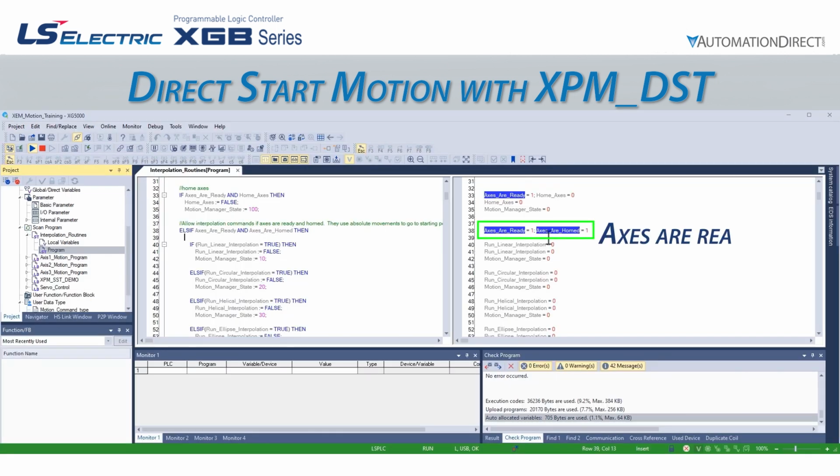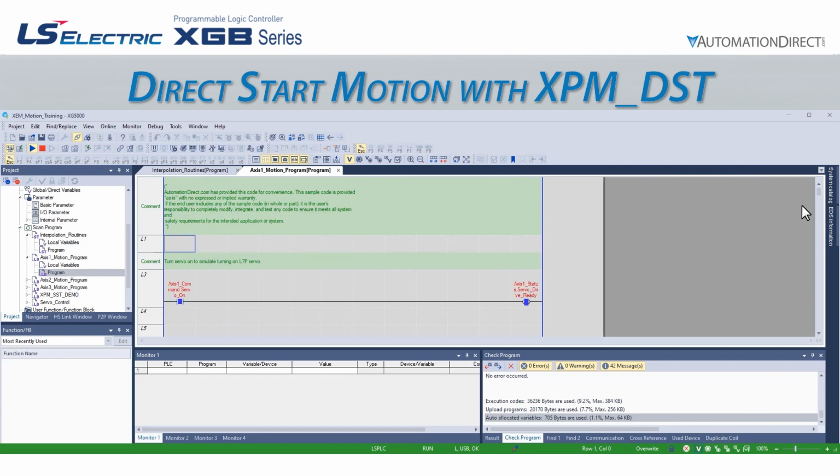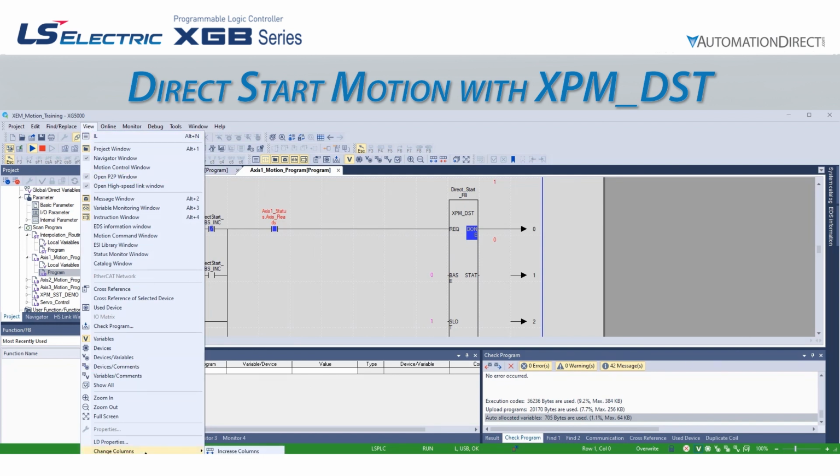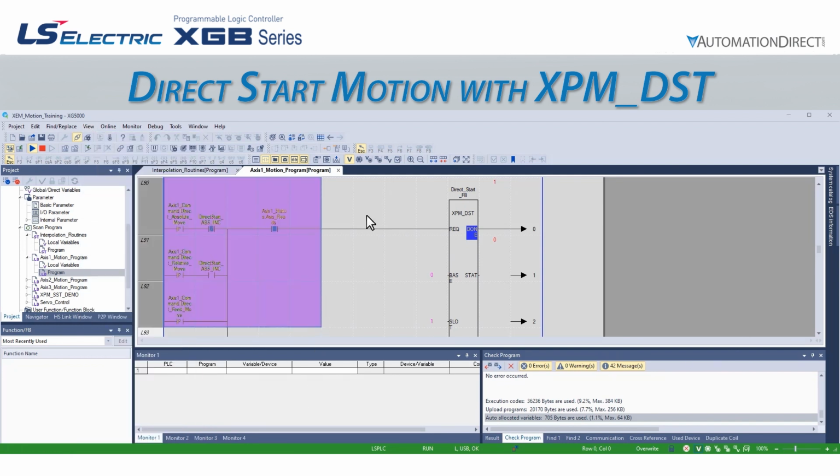We also have powered up the axis in our logic and turned the servos on, which are figurative in this example. Most of the motion profiles in this project are interpolations using indirect start function blocks. However, we do have a direct start function block for each of the axes. If we go to the Axis 1 motion program and go to line 90, we see that we have an XPM DST function block. Currently, we don't have enough columns to see the entire line of code, so let's add a few columns to our programming environment. You can go to View, Change Columns, Increase Columns, or we can go to the icon of a series of cells with arrows pointing outward.